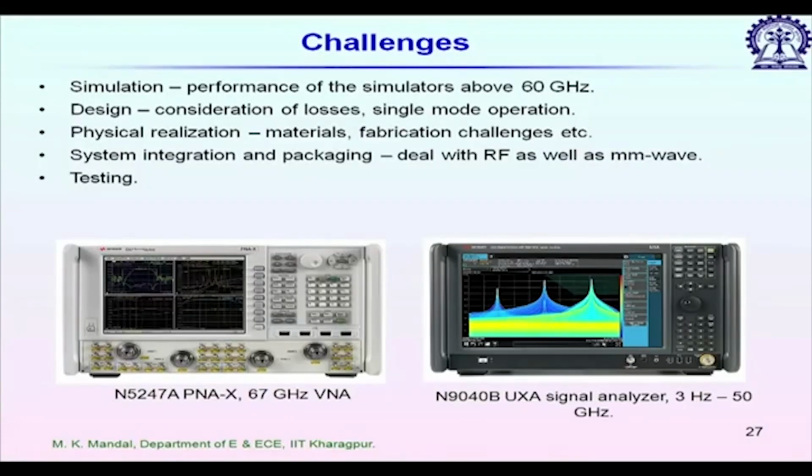For any given waveguiding structure, we prefer that there is only one type of mode present in that structure, and no excitation of any higher order modes. Otherwise, these higher order modes will increase the loss of the system and also dispersion. So, we have to avoid these higher order modes.